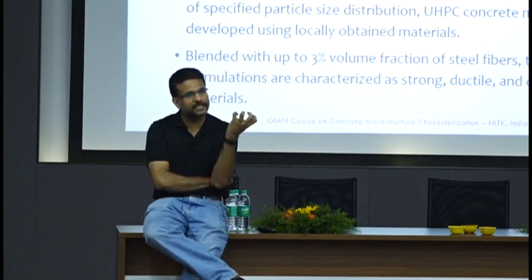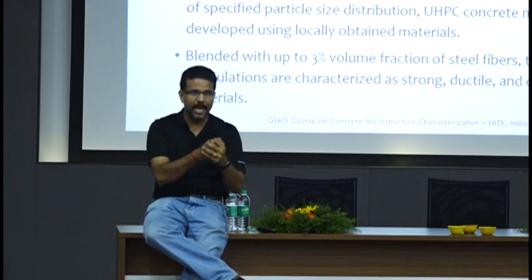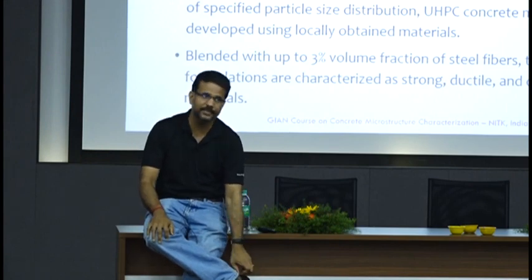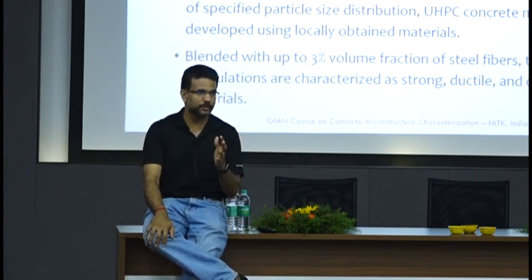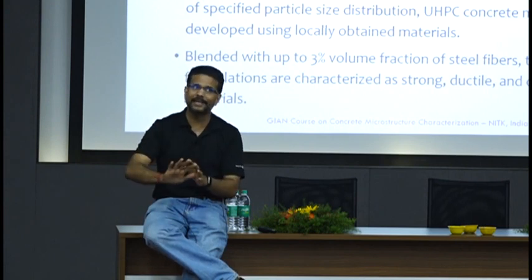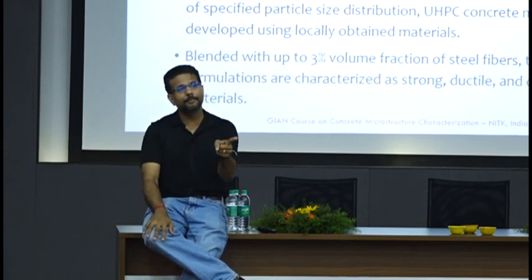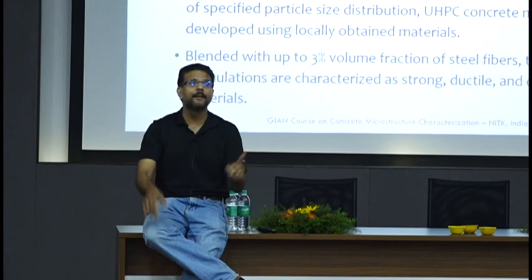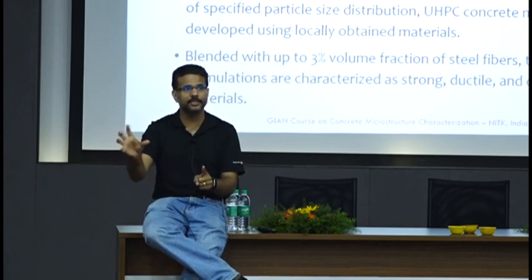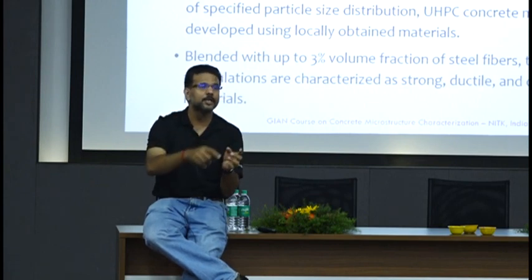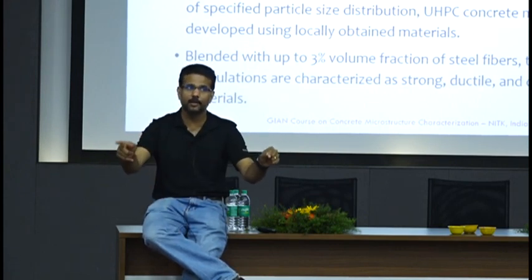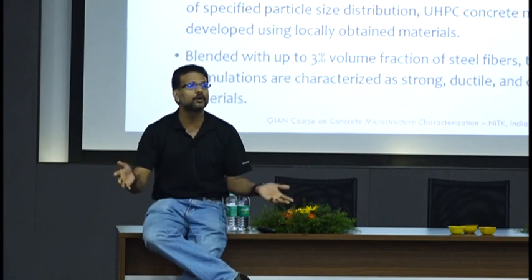Strength comes from the physical portion, which is the packing, and the chemical portion, which is the reactivity. There is no way that you can separate the contributions of both. Your chemical part is time dependent, your physical part is really not time dependent, but when the chemical contribution changes, when you have reaction products forming in different parts, your physical packing also changes. So anytime one changes, the other also changes, and there is no one-to-one correlation.